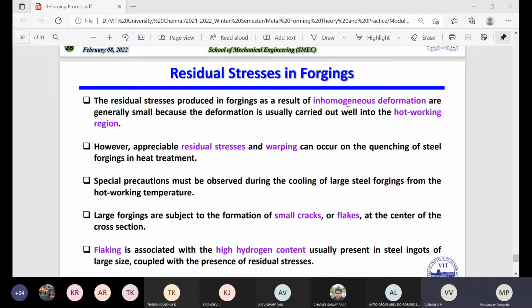So if you think about what I told you about somewhere the material being found brittle, that red hotness, if you remember that word I was using. So here also sometimes we are not finding it homogeneous everywhere. The moment it is not homogeneous, then it will be difficult. That's why I recommended that sometimes when we are doing heat treatment, you have to increase the temperature up to a certain limit with a certain rate. Then you have to hold it. While you are holding it, maybe 1 hour or 2 hours, if it is not homogeneous, probably it will become homogeneous in that period. Then you will find this is the accurate one, and after that you can go for the cooling at a certain rate.